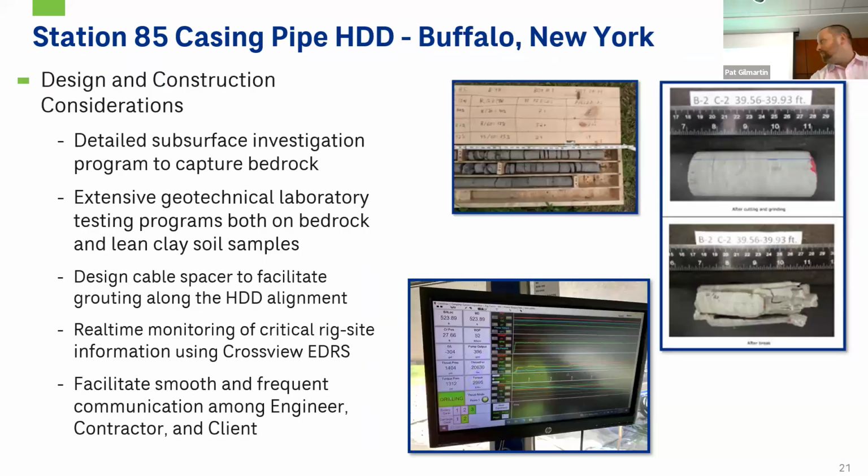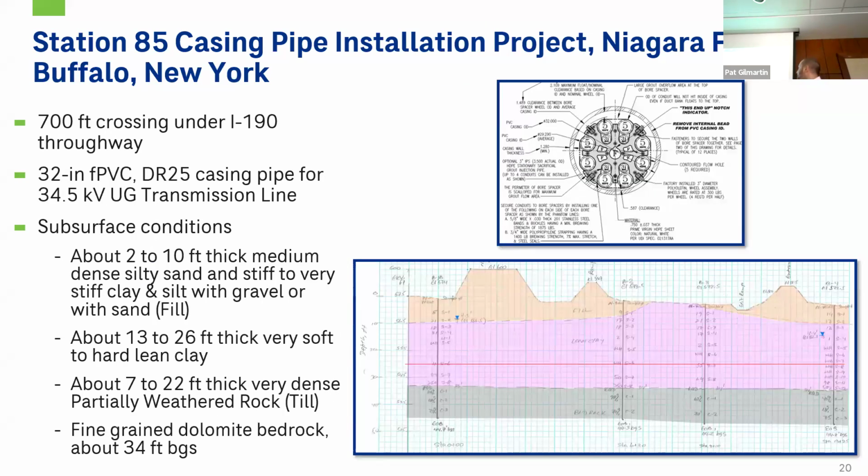And so actually going back here, the way that we ended up doing it was you install the larger pipe with this casing pipe that was 32 inches. And I believe there were either 8 or 10 smaller conduits of about 3 to 4 inches that were housed within a casing spacer alignment. And so once those casing spacers were installed, we ended up grouting the annulus similar to what you would do with just a typical duct bank that you lay down.